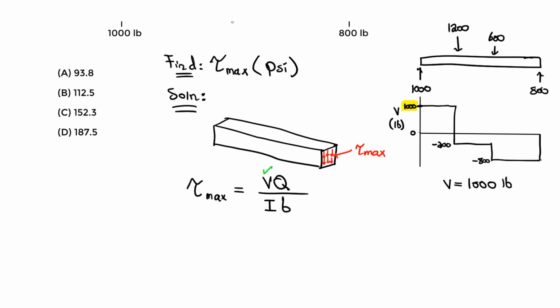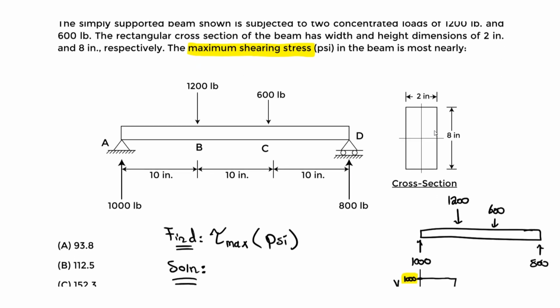Q can be complicated. We'll learn it for this simple example, but you can apply the same procedure to I-beams, trapezoid shapes, circles, T-beams, non-symmetric I-beams, and so on. But this one's going to be relatively simple, because you just have a rectangle that's symmetric about the middle axis. That middle axis is also called the neutral axis.